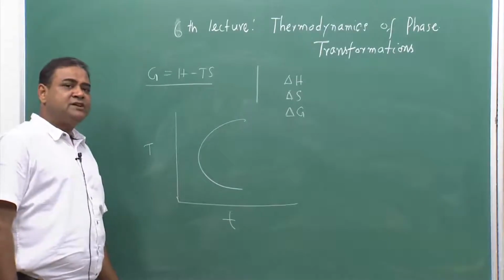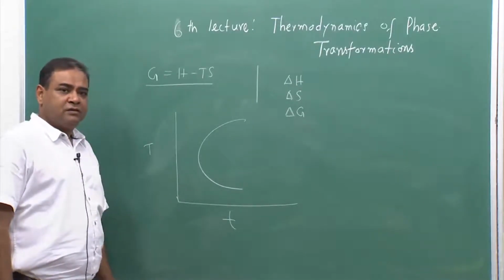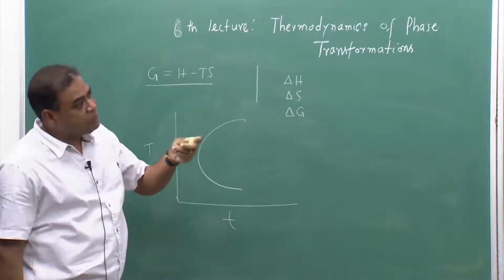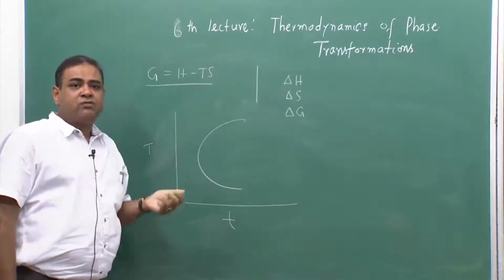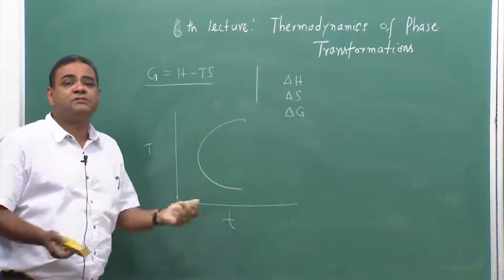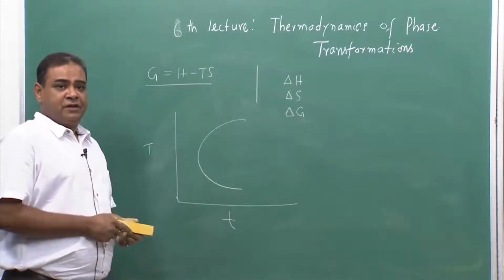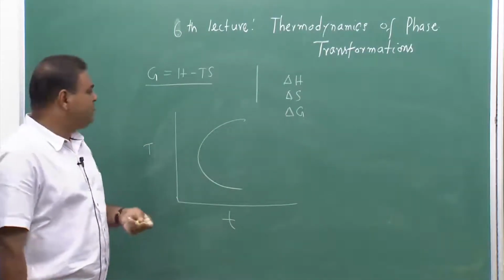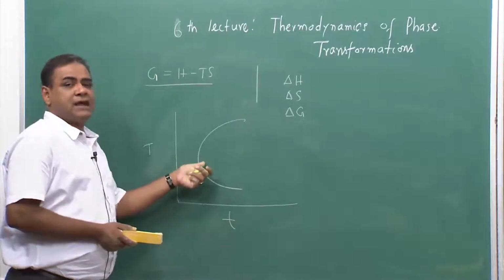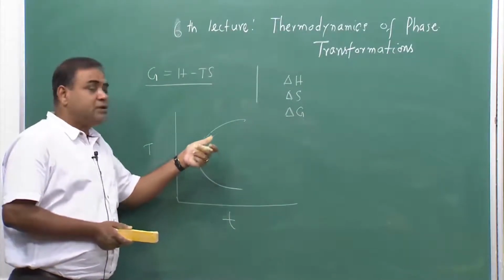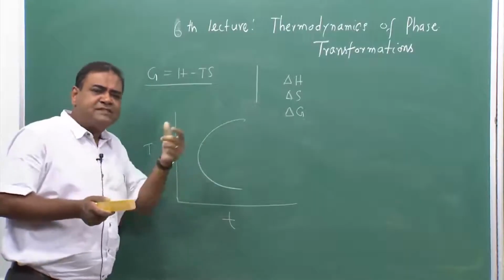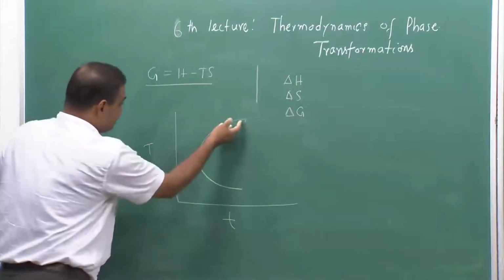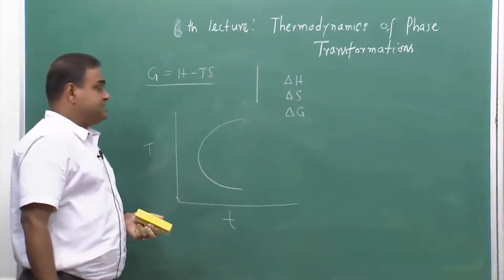At the same time, we can do a simple calculation from simple thermodynamic data. For example, the data required would be del H m, T, and the viscosity value. So, those are measurable quantities. If we use those parameters, we can get this TTT diagram, and in most cases the experimentally found values and theoretically found values match with some little adjustment. But the nature of the graph remains like this, which is a C curve, this is a TTT diagram.